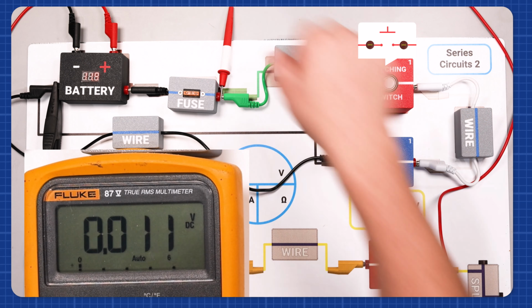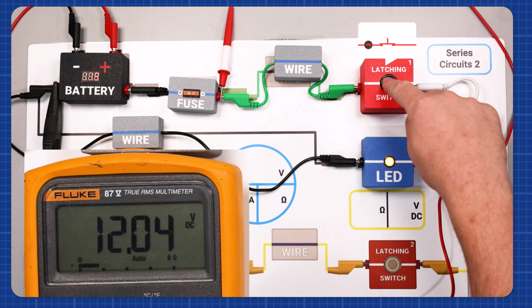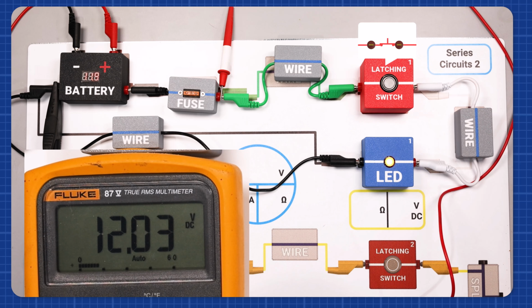Step 2. Measuring voltage at the fuse. At the fuse, the voltage is approximately 12 volts when the switch is open. This is because the fuse is directly connected to the battery's positive terminal and the potential difference is present at this point. When the switch is closed, the voltage at the fuse remains at 12 volts. This indicates that there is a continuous path to the positive terminal of the battery through the fuse.